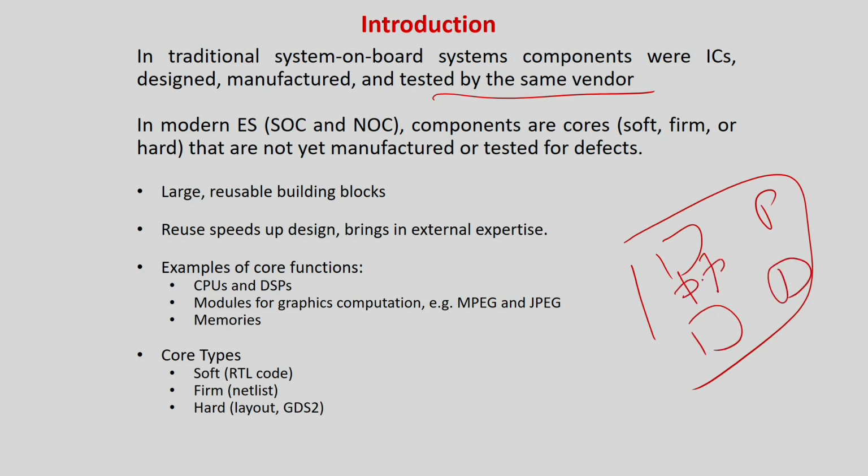If I put some kind of multiplexing arrangement, I do not know much detail about these IP cores. And also, fabricating some extra multiplexers inside a chip may not be as easy as it was on a board, and also not very ad hoc. So, I should not say it's more difficult, because putting an extra multiplexer in a board as well as a die, this silicon chip, is almost equivalent in difficulty level.